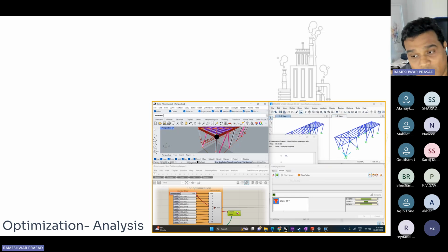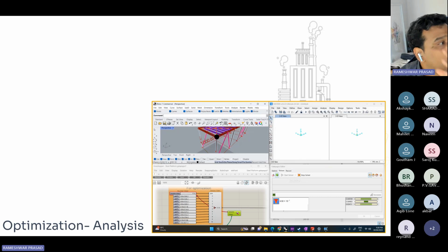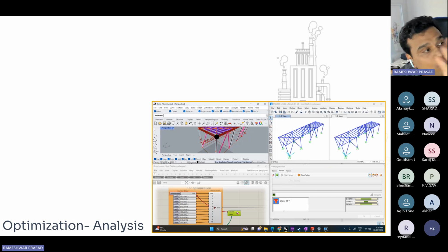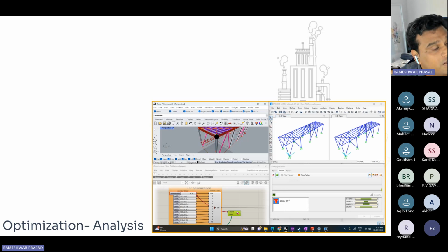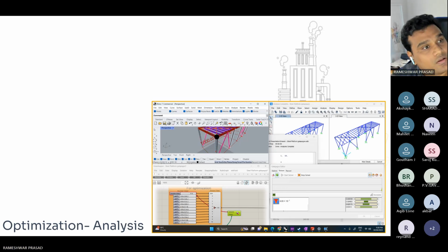By varying, like I use the column sizes. You can use the thickness of the core wall, the dimensions of the column in that particular direction of the drift, and you can actually do multi-variable optimization as well. That means you can control the thickness of the core wall and the thickness of the columns if both are contributing to the lateral deflection.